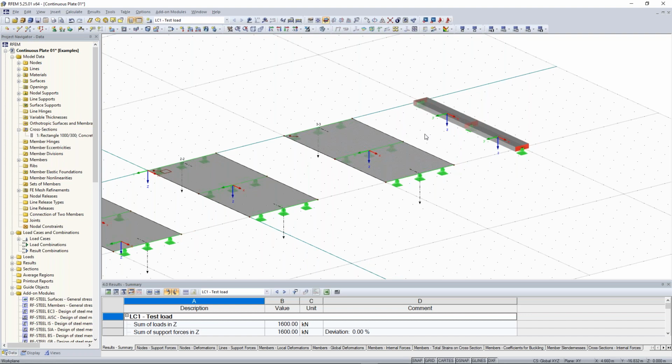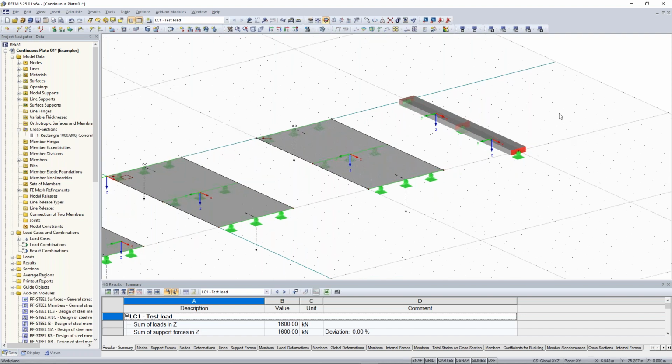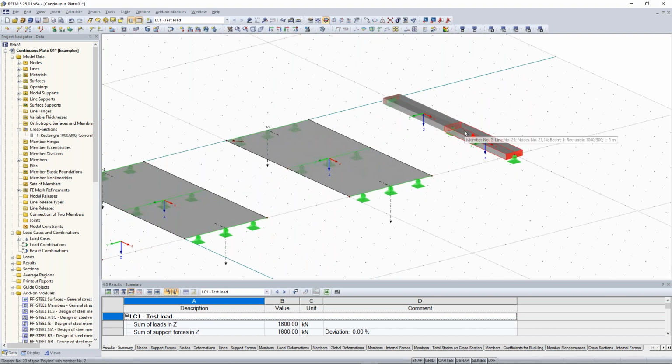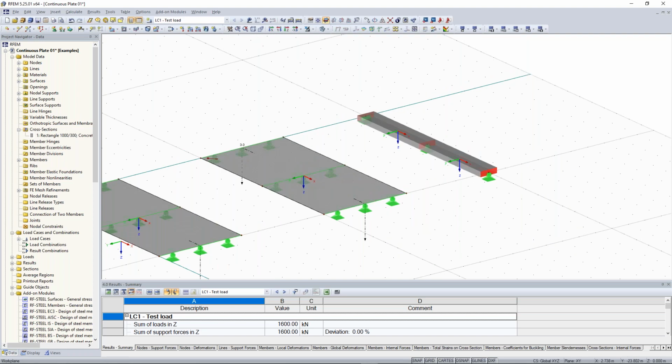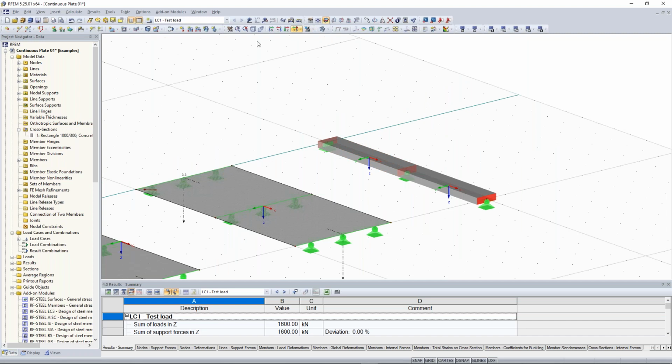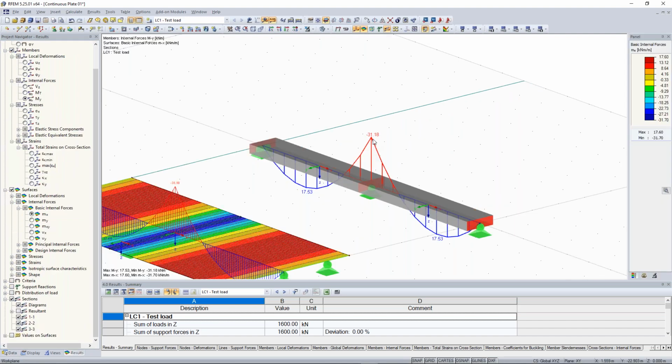Now, normally in your studies you do some hand calculations. That's pretty common, and therefore you also use some tables or calculators and so on. When you calculate the support moment of a two-field beam or continuous beam, you may get other values. So let's watch the results again. Normally you would get a support moment of 31.25 kilonewton meters. But in this case, just 31.18.